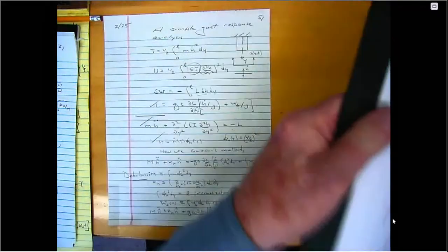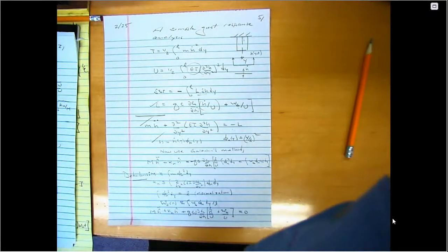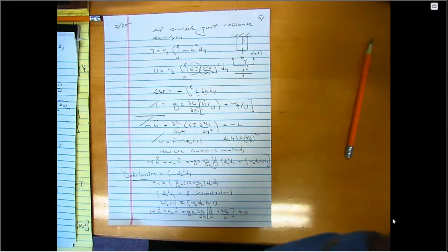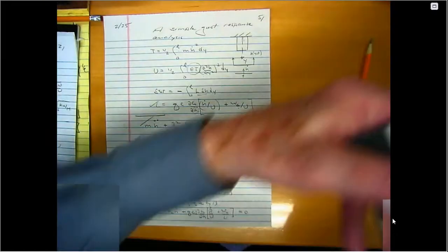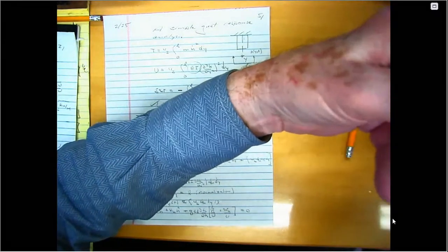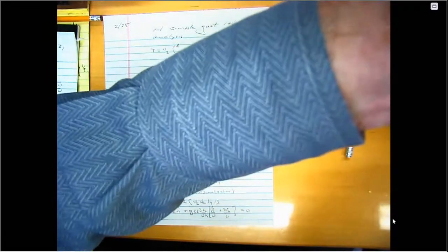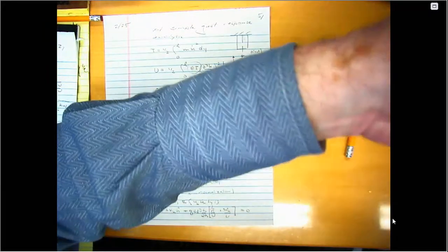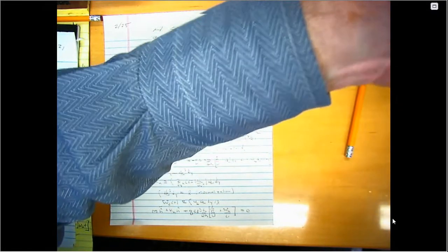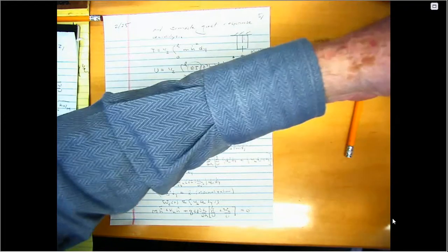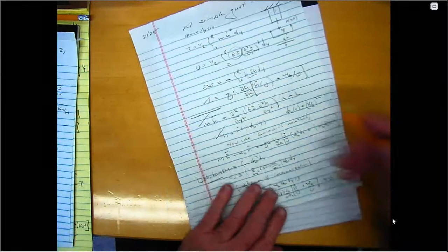That means if I clamp this, it can bend. It's bending. I'm not doing this right now. Sorry about that, Stockholm, you can't see this. But your friends here in Durham are going to tell you that it's okay. You're spinning under gravity, right? But I'm clamping it, so there's 0 slope here, right? If I clamp it all along this edge, not only is there no deflection, there's no slope. The slope is 0 as well as deflection. Okay? All right. So that's why I choose this function.